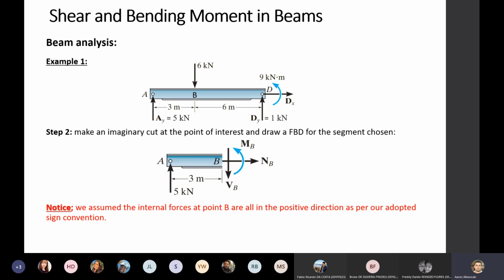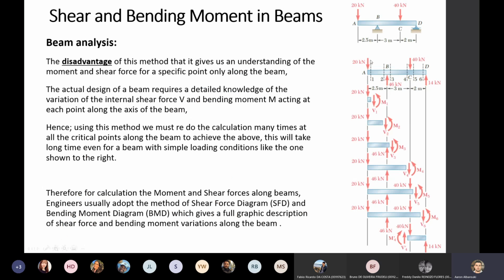And maybe you could tell here that's where the point is applied and everything else is okay, which is not accurate, by the way. But if you may assume that, what about if we have a large beam with too many forces in many different directions? How would you know where is the luckiest spot to take that section that will calculate everything for you? So rather than doing that, what we have to do to come up with that argument for actual designing of the beam, to avoid that, we have to make as many sections as we can. If I have a beam like this, is it the worst case scenario here on the support or there, I wouldn't know. So what we have to do for this situation here, we have to take a section here to check this portion between A and B. I have to take another section maybe just here before the reaction, see how the shear forces are developing in the beam.